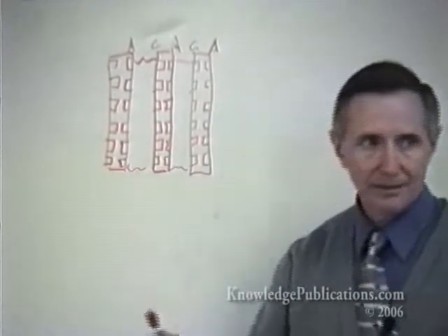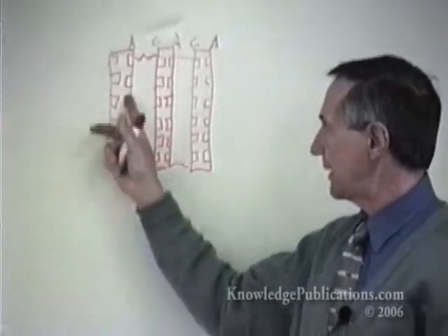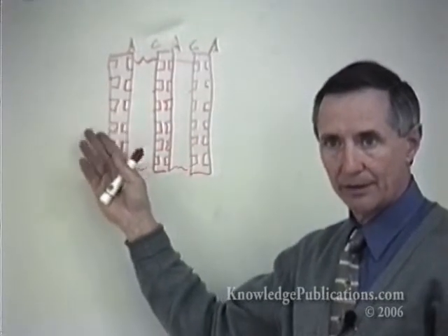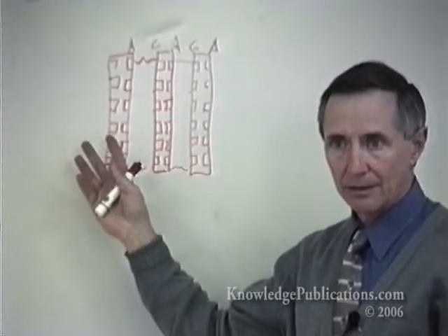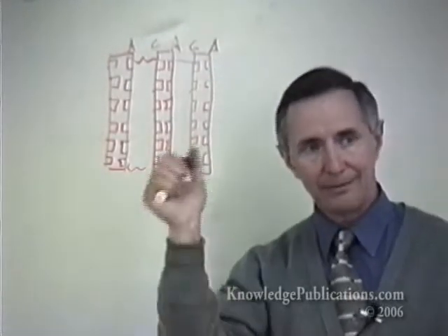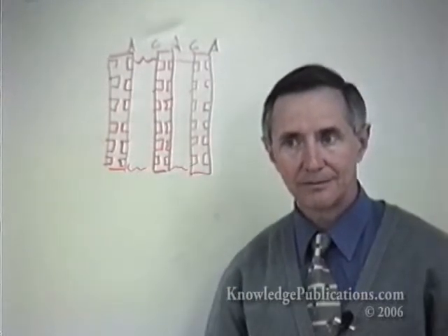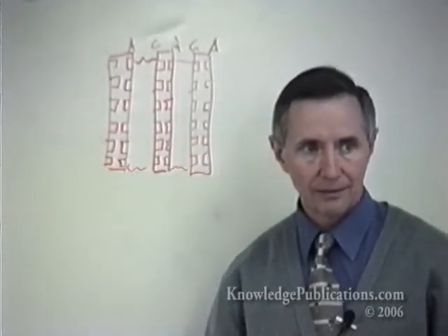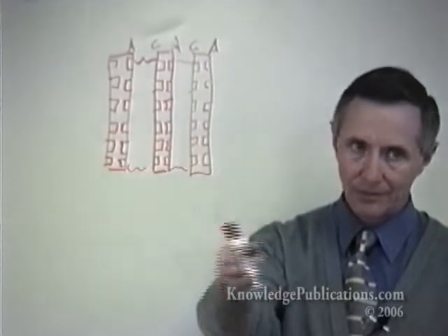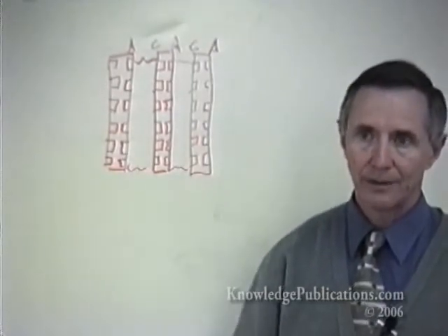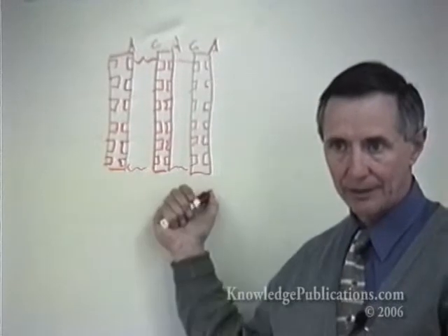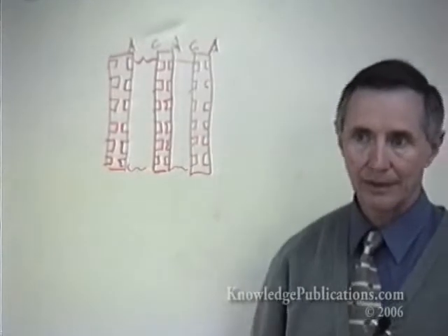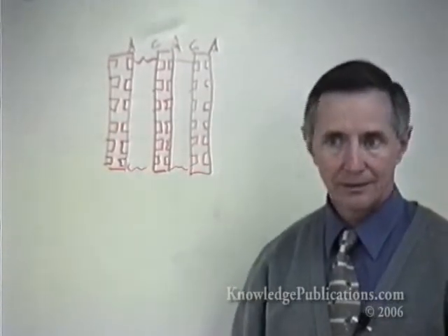If you're really going to the nth degree of compaction, you'd build these systems up, this flow and electrode bipolar unit, also as the water heat sink. So you could immediately go to Jerry's application and say, hey, I can make your electricity and give you hot water or steam, which would be a very good thing. And you could then determine between the two of you what the best market was, the ratio of voltage, the number of cells that you stack up in the bipolar arrangement, and where the water goes to satisfy a water heating or laundry or space heating need.